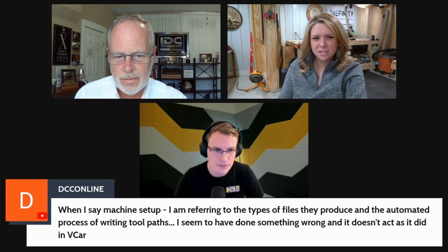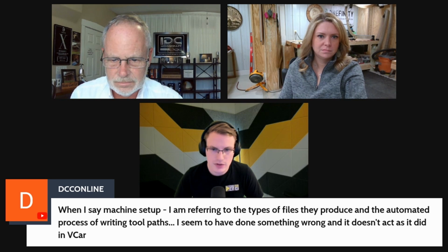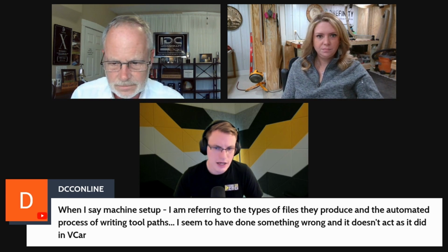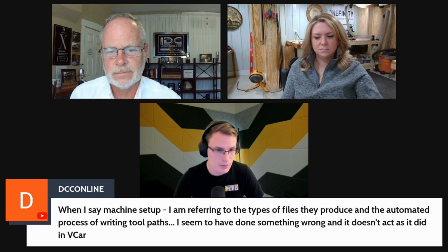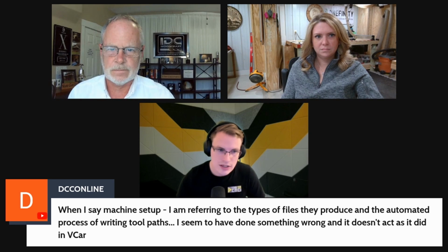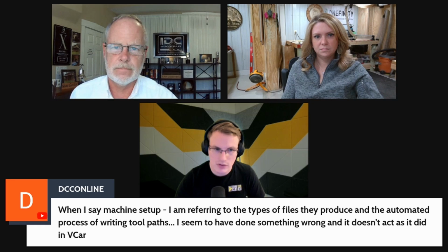Okay, there's a second question follow-up. I'm going to go ahead and bring that out. Oh, my apologies. He says he's referring to the types of files they produce and the automated process of writing toolpaths. I seem to have done something wrong. It doesn't act as it did in VCarve. Yeah, that shouldn't have changed. But if you're talking about maybe templates you used before, if you're automating toolpaths, you have to make sure the layers are associating with the toolpaths.